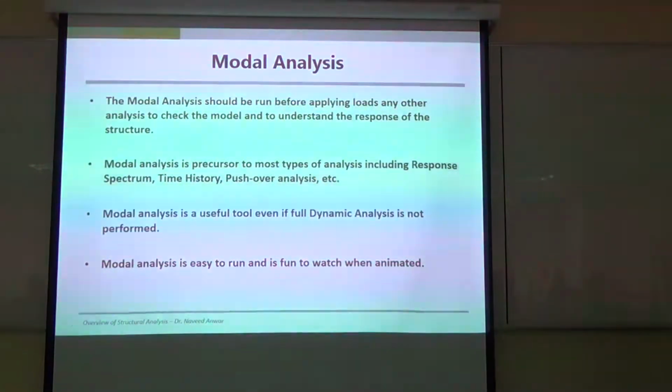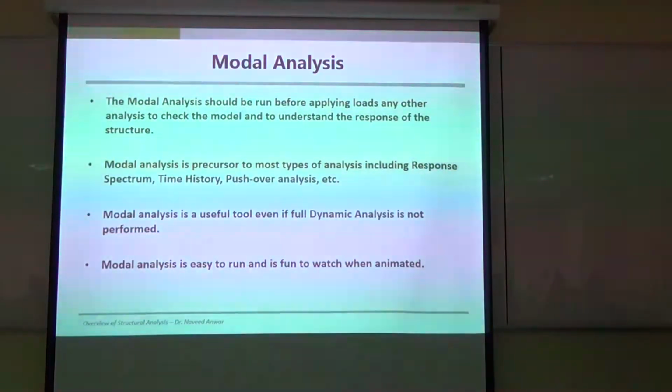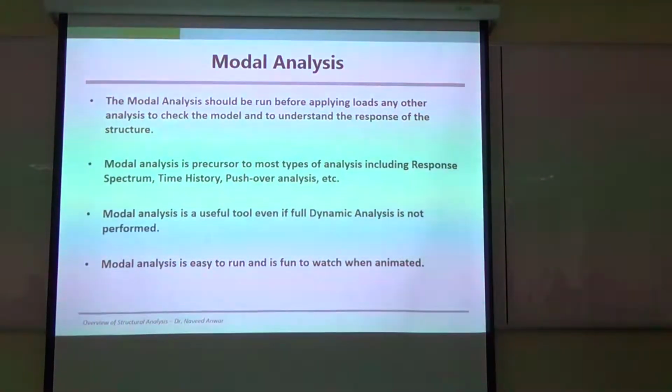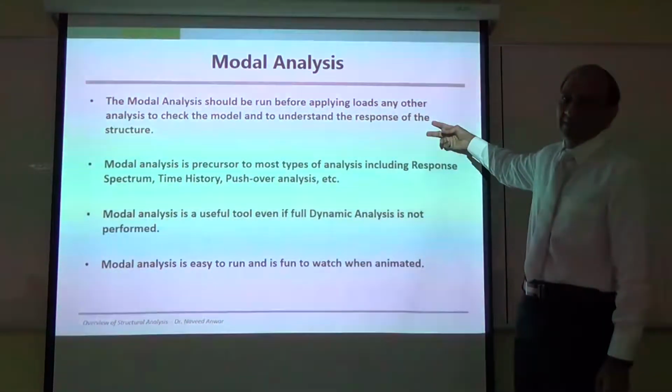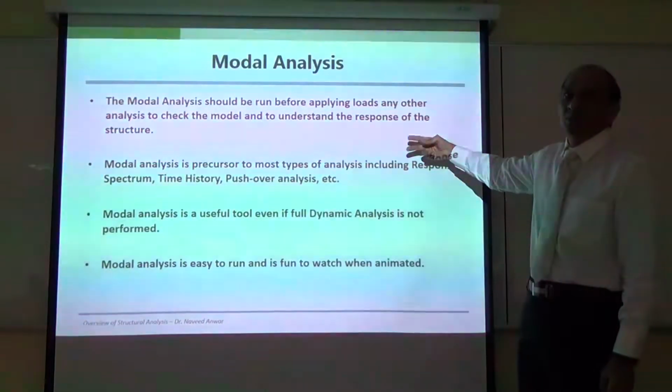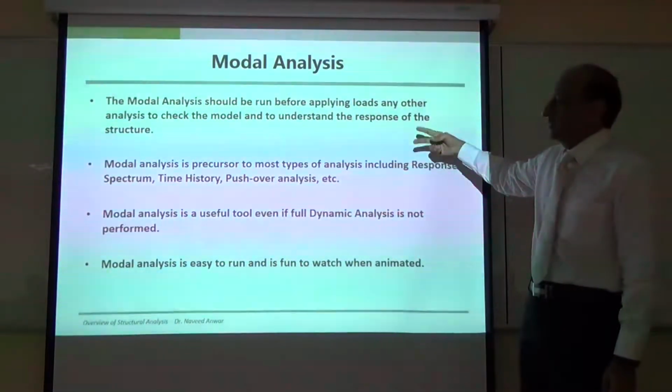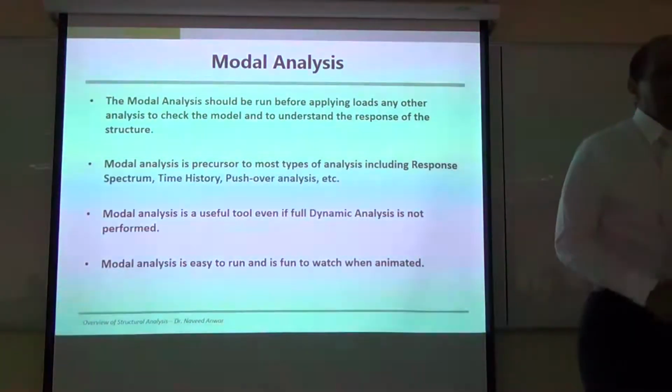So that kind of big error can be the same problem with units of the modulus of elasticity. Many people make a 10 times error in the units of the E, whether it is 10 raised to power 7 or 8, depending upon centimeter or millimeter, whichever they are using. So they sometimes do make that mistake and enter one zero more or less. That can easily be detected if you run modal analysis, because stiffness will be wrong by 10 times. So you will know something went wrong. So running a modal analysis is most important, and you should know how to read the modal analysis and make a decision whether the structure is okay or not.